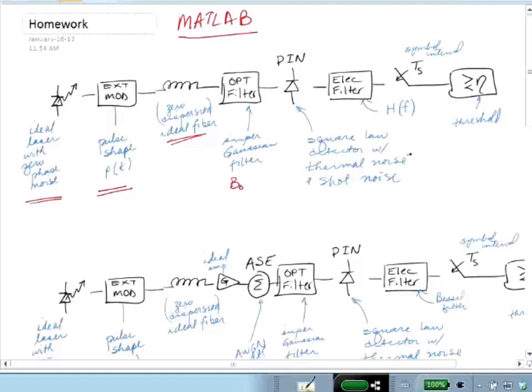And of course, in your MATLAB code, we're adding the thermal noise and the shot noise, and we want to make sure that we're adding it in the correct way. So one of the things that we'll be validating is using the MATLAB code to run a Monte Carlo simulation of what the noise component is, and then you'll also be plotting a theoretical calculation of what the bit error rate is for these thermal and shot noise levels you've set, so that you can make sure that your code is properly run. I'll tell you, I provide 90% of the code, and the 10% you're missing is about normalizing signal-to-noise ratio. It's the largest source of confusion that I've seen with my students, how to correctly normalize the noise so that you can correctly interpret your results. So the validation is focusing on that error, which I think happens quite frequently.